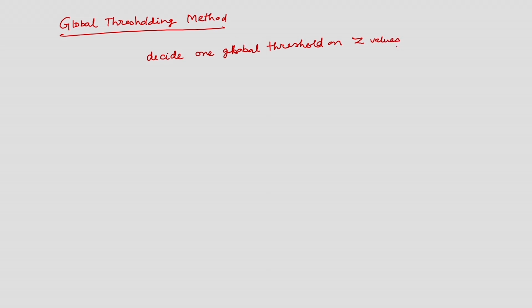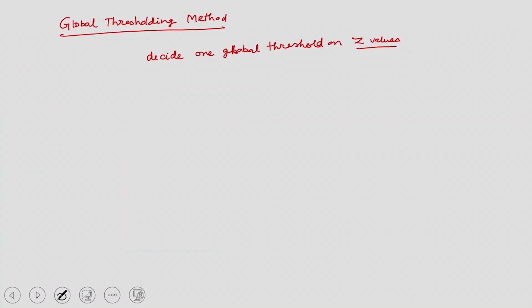The purpose is, whatever points fall above this global threshold, I will remove from the digital elevation model or maybe the TIN model. If I consider it very appropriately, in one attempt it will remove all the points belonging to trees or buildings, and then we will have the real terrain that was originally there when there were no trees and no buildings constructed.